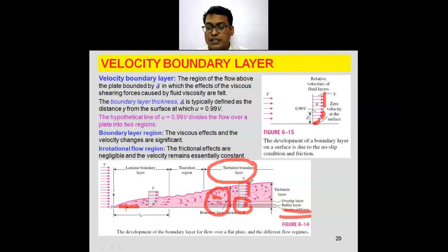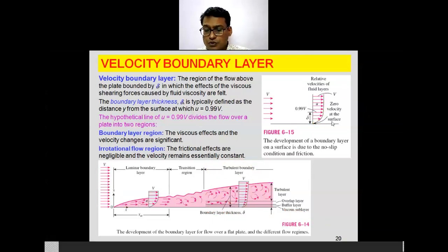That is why the velocity profile in the turbulent region is more flat. More flat means uniform. Here the velocity gradients are flatter, they are uniform. Here you get a flatter velocity profile. Here also in this upper section, you can see the flatter velocity profile. However, in the lower section, you have a slight curvature. So the velocity profile in this turbulent region is flatter than in the laminar region.